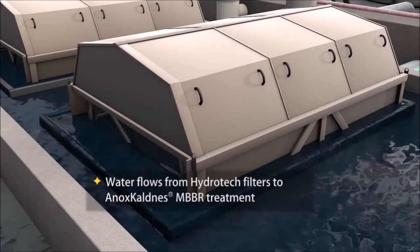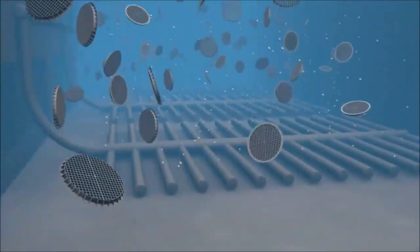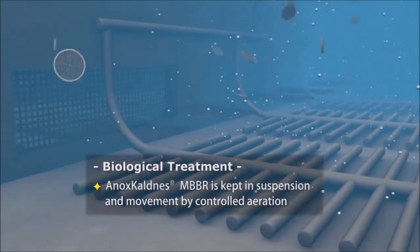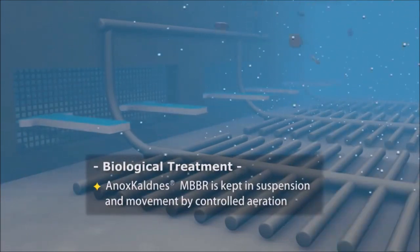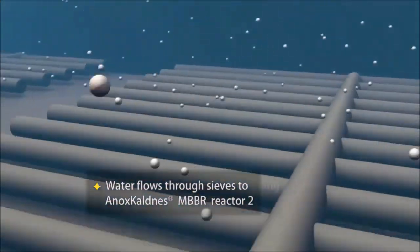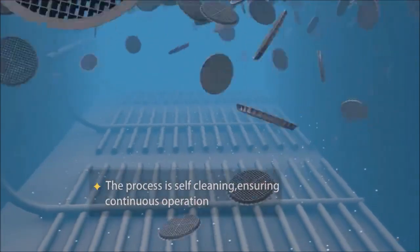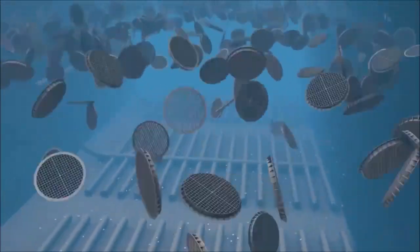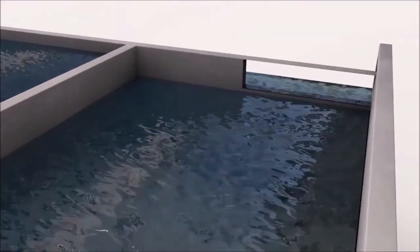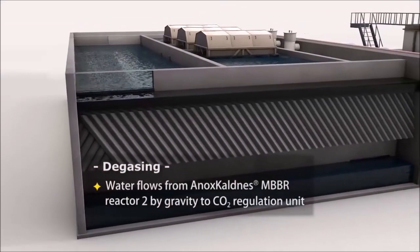Once the slurry is removed, the water is taken for biological treatment. In this place we have the bacterial culture, and using this bacteria the water is cleanly treated, like with a probiotic bacteria. After the biological treatment, the water is subjected to oxygen enrichment using aerators. Once the oxygen is enriched, the water is subjected to degassing, because it has many foul gases